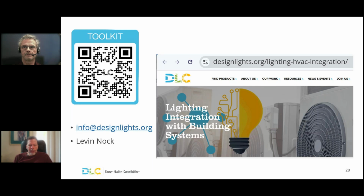The highest level would be using the BMS front end software to talk through an API directly to the lighting system user interface or to the supervisory controller. So there's three different ways to do that. Depending upon the project requirements, all three of them could be done. Most vendors would be able to support any of those three mechanisms, but it really comes down to a product selection and specification project.